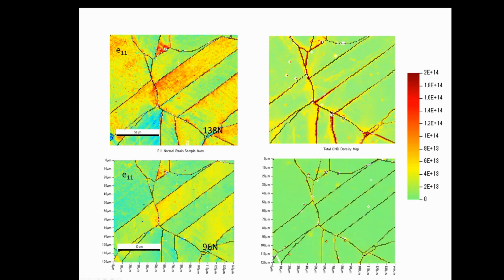Those that are interested in recrystallization in materials will be interested in these local, highly concentrated, very small areas with high concentrations of stress, and that's where recrystallized nuclei will come from. They're not all on the grain boundaries. Some are inside, and one would have to investigate why they're there. So it's not only how you get the patterns, but how you interpret them and how not to be misled. So you want to try and put as much information together at the same time as you can.